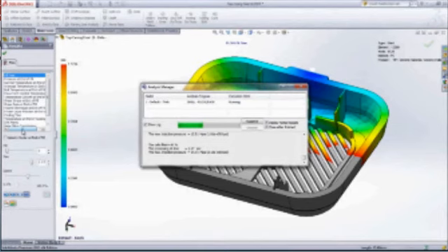The Plastic Manager also provides some great and valuable feedback for mold designers. You can know what percentage of the model is filled, the processing time, and what the maximum pressure requirements are, and instantly see if it exceeds your machine's properties. If you find out that the maximum injection pressure is higher than the maximum pressure of the injection molding machine, you will know that this part is unlikely to be manufactured properly without a design change, a process parameter, or maybe even a material change.